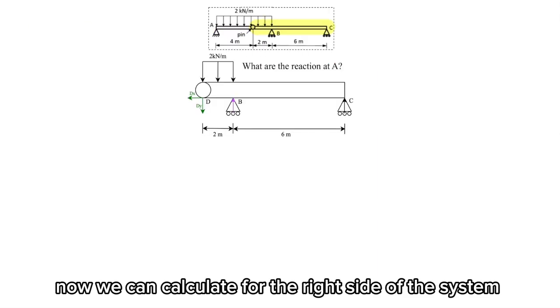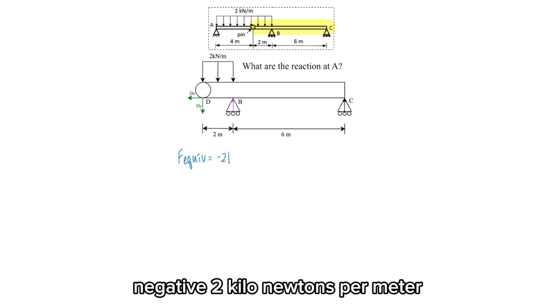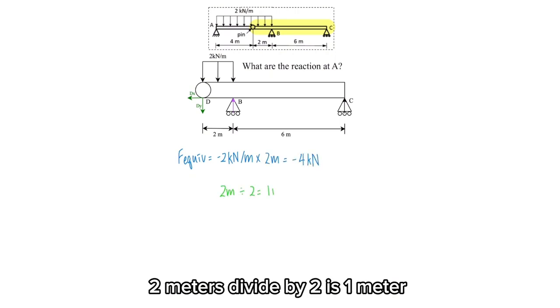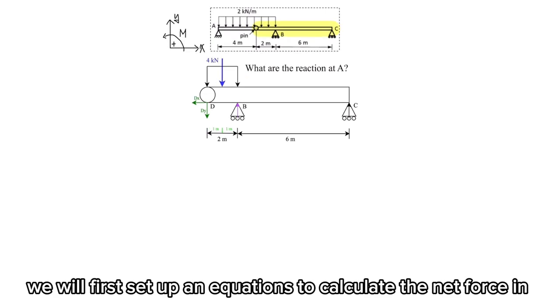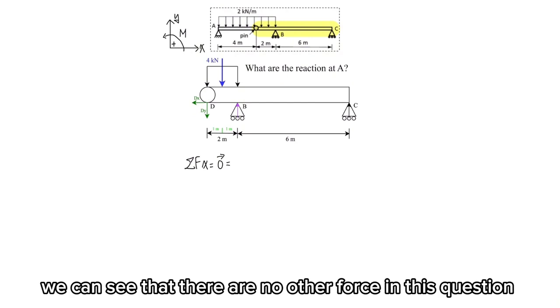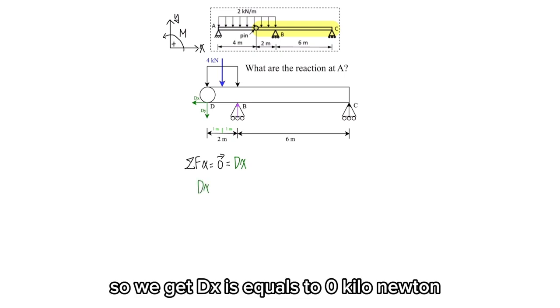Now we can calculate for the right side of the system. First, we will find the point load. Negative 2 kilonewtons per meter multiplied by 2 meters equals negative 4 kilonewtons. 2 meters divided by 2 is 1 meter. We will first set up an equation to calculate the net force in x direction, which must equal 0. We can see that there are no other forces in this question acting in the x direction other than DX, so we get DX equals 0 kilonewtons.